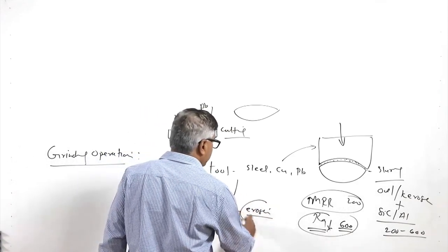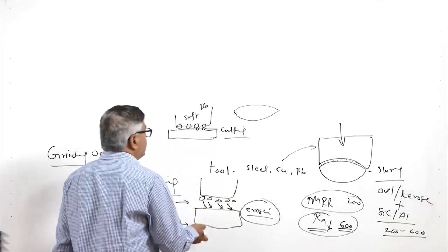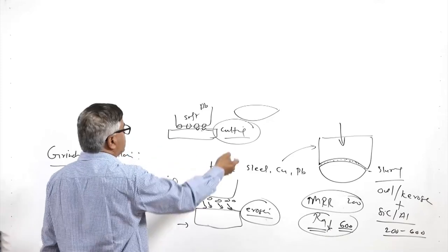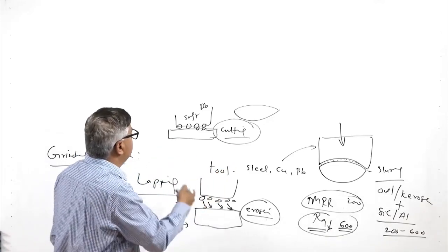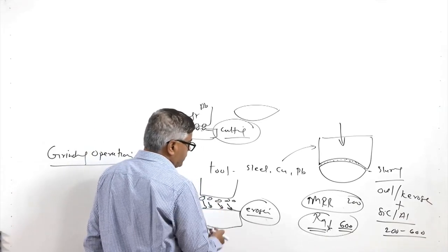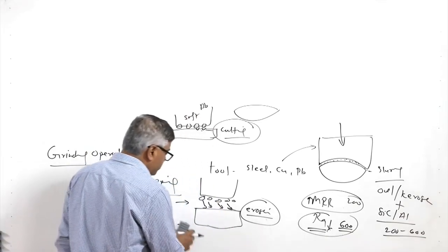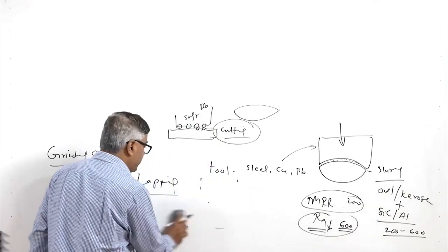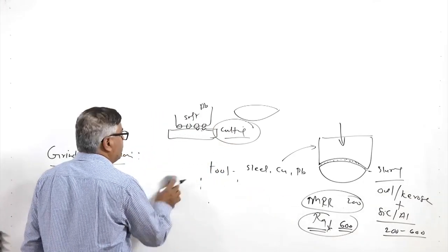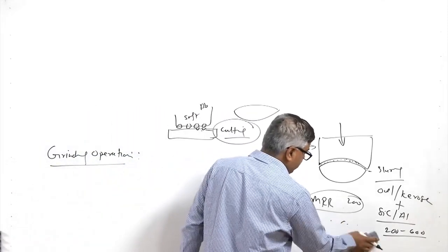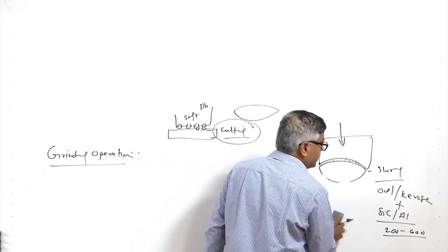So, these are the two mechanisms considered for removal of material. One, when the abrasives get embedded in the surface of soft tools, basically cutting, and another, when the moving abrasives hit the surface of the workpiece and cause removal of material by an erosion kind of process.